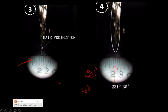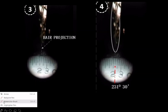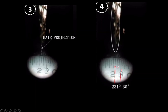So how to read? I'll show you another time. So this is 230, right? This line is 230. This is 231, 32, 33, 34. Okay. If the crosshair comes with these small lines, what are they? They are minutes. Okay. So the least count of the prismatic compass is 30 minutes. So if the crosshair is here, then your reading will be 230 degree 30 minute. So now, where is your crosshair? The crosshair is here exactly. So it is 231 degree 30 minute.